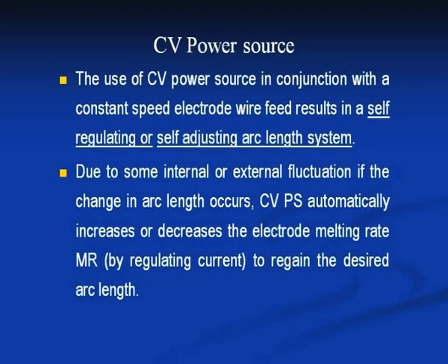The melting rate of the electrode can be expressed by the equation AI + BLI², where A and B are coefficients considering the ionization potential, the type of metal, the flux coating, etc., I is the welding current being used, and L is the electrode extension through which current passes for stabilizing the arc.